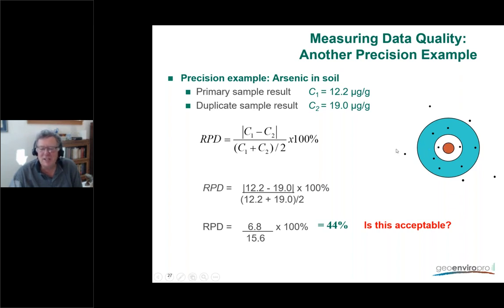If you really want to understand the slop in your data, you need to have more analysis of that single sample, and we are rarely going to do that. What we sometimes do is pool our data sets, and maybe Ryder can comment on this when I'm done talking. If we have the same population of soil, we can pool it and get an understanding of the variability by looking at multiple samples. And this is again assuming we have a simple singular population, therefore a single target.